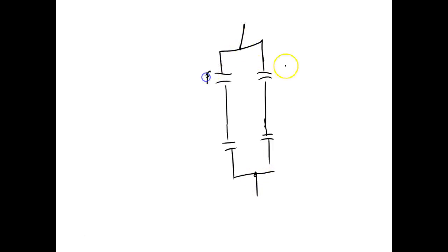And this would be forward, and this would be forward. And then this right here would be reverse, and this would be reverse. And your DC motor armature is right here in the center. And if this is minus and this is plus, if we code reverse, then the current flow is in this direction for reverse. If we go to forward, then the current flow is in this direction for forward.